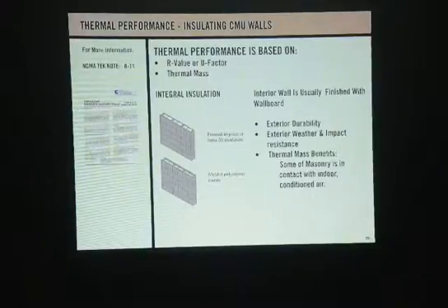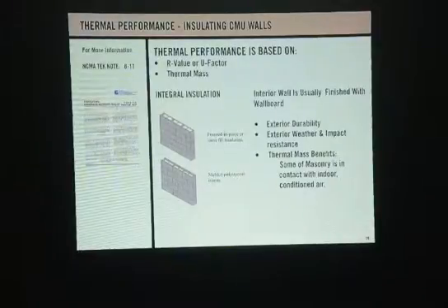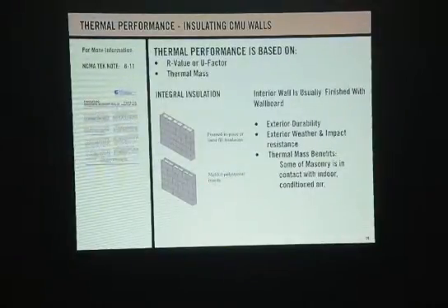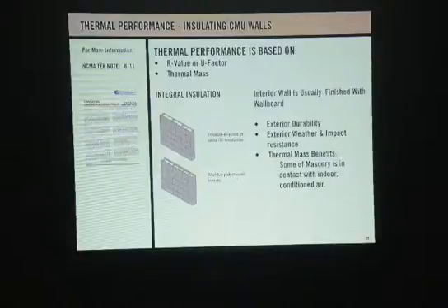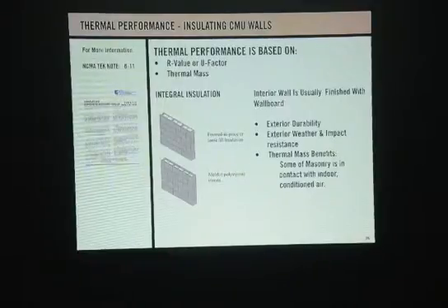Does it have to have mortar on it? Yes, because if it's 8 by 8 by 16, it's 7 5/8 by 7 5/8 by 3 5/8. So you do need to fill the voids with mortar also, but it's about 40% more to have a pre-insulated block than not to have it.